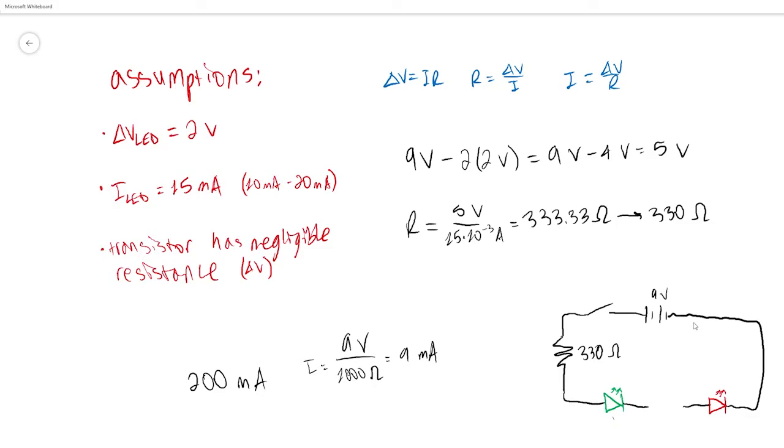The main component of this, then, is the other side of the circuit, which is the transistor side. For that, we're going to connect another 9-volt battery into a switch so we can turn it on and off. In that, we are going to put our other resistor, which is going to be 1000 ohms. And the main part here is going to be a transistor. We are using an NPN bipolar transistor here, and we can draw those connections like so.